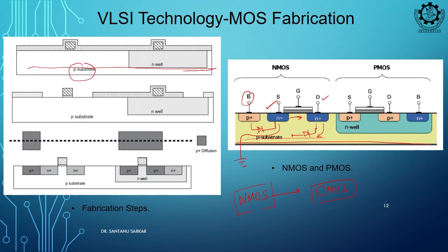This current is not of my interest, right. The channel current is of interest. The current wasting to the ground line is not my intention, right. So, I should stop this current. So, if source is grounded and bulk is also grounded, they are virtually shorted. So, in this PN junction there will be no reverse saturation or leakage current. So, that is the idea behind doing this, right.